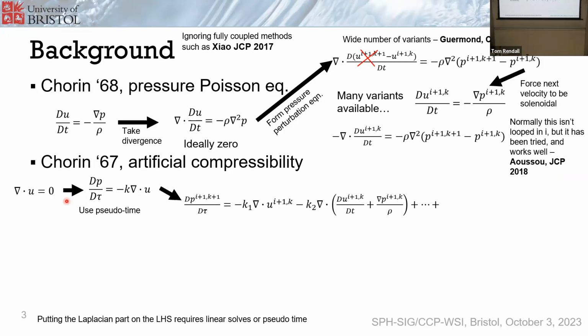So an interesting aspect to this, artificial compressibility has been explored for SPH, but the spatial reconstruction in SPH is quite vulnerable to noise due to its varying nature. Your particles represent your grid, if you like, and so it can give you quite spatially noisy pressure results.